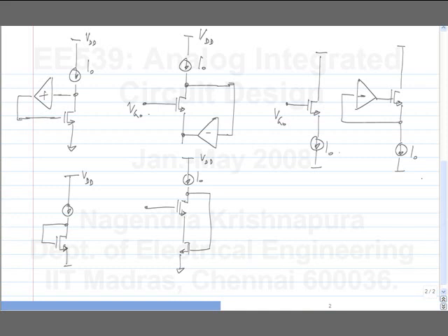You have to find the current source somewhere, but once you have a current source, you can connect it up like this. The fourth one, I will not write the complete circuit now, but you can in fact do something of this sort. I will not yet complete where the drain of the second transistor is going. In all these cases, we started off with trying to bias this transistor M0 with a current I0. In this case, we have an additional transistor M1, which also happens to be biased at I0. Here also we have M0 and this is M1. We haven't shown the biasing for M1 yet. We will look at it soon.